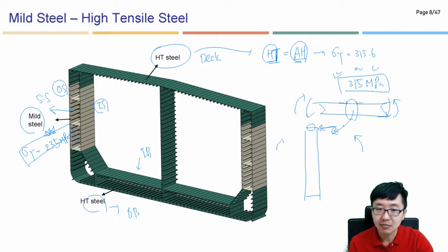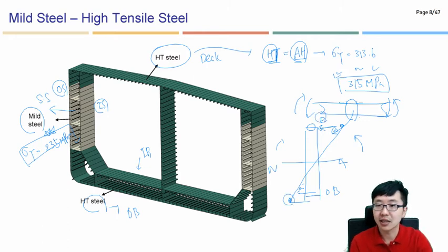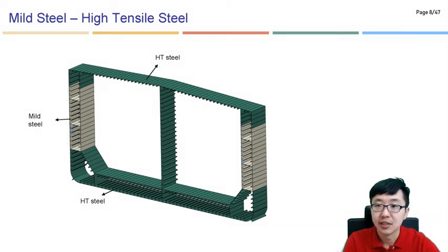At the same time, the outer bottom part will be tensioned, isn't it? So anyhow, this is the neutral axis, for example, and a higher value of stress will be applied to the deck as well as the outer bottom. That's why they have selected a different material here for the outer bottom and deck, but just normal materials here.